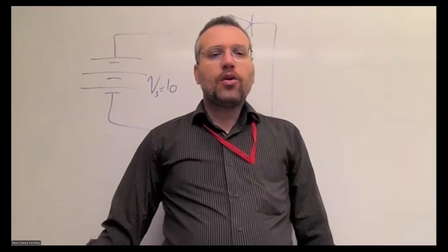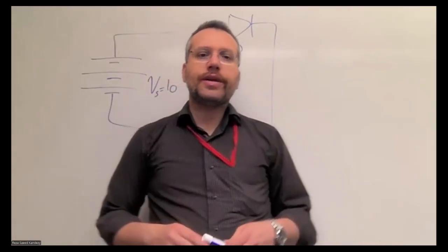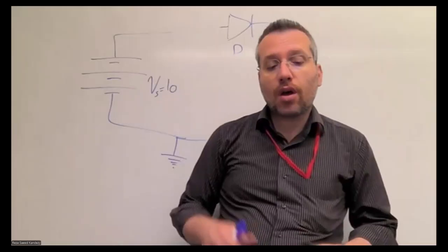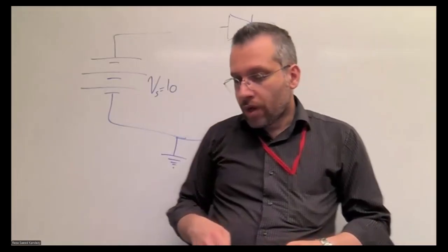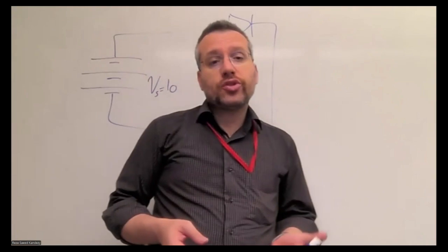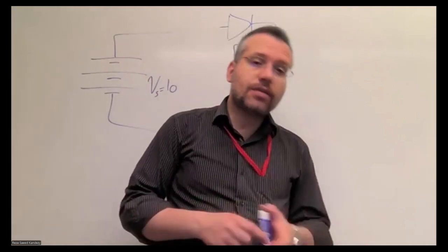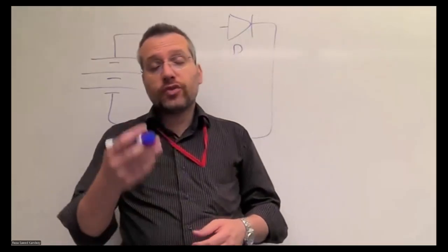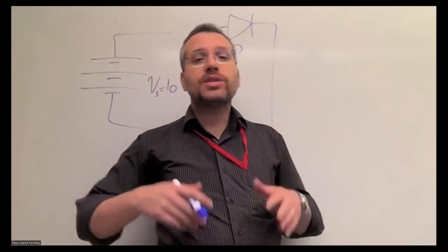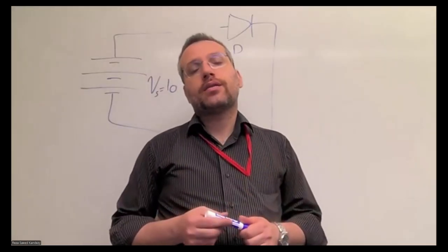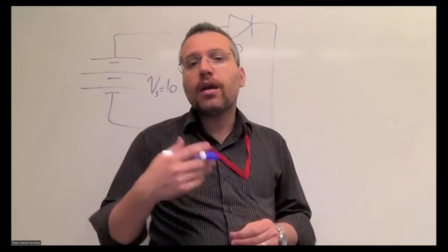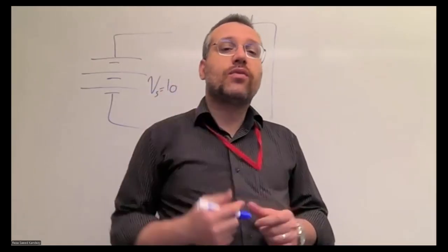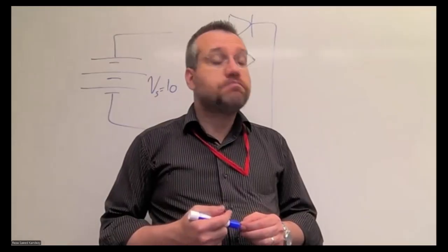Now in this part, let's talk about the minimum series resistor that we need. What that means is, in any electrical circuit, as we said when we talked about the datasheet of a diode component, there is a maximum current that the component can conduct. We never want to reach that maximum safe current.